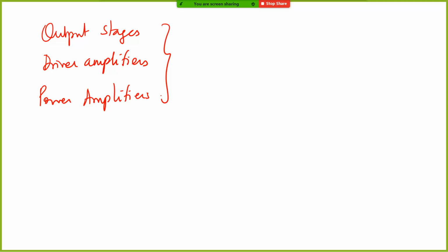Now, these power amplifiers are things that we encounter almost on a daily basis. For example, if you are listening to the lecture over your headphones, there is a power amplifier sitting there which is driving your headphones load. If you remember, sometime back in our course, we talked about emitter followers and source followers, and I mentioned that emitter followers are good circuits which can drive resistive loads. Usually, I also gave the example of headphones or speakers, and they are resistive loads. Their impedance will be around 100 ohms or something lesser.